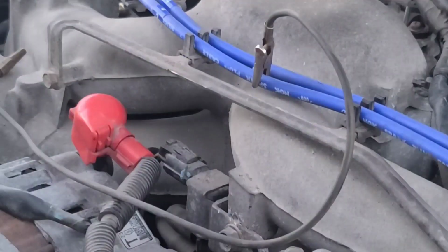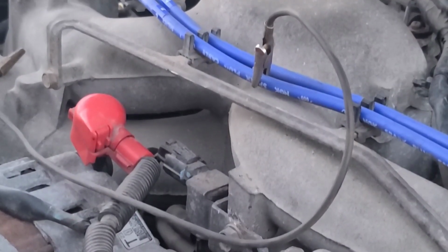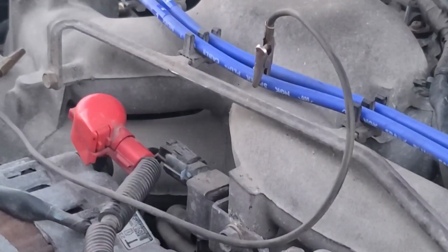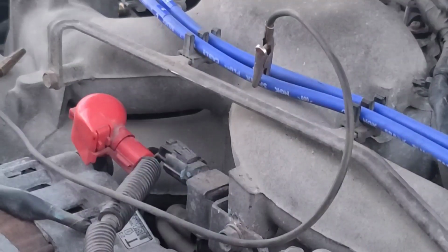So I reviewed the video and I didn't see any spark. I didn't hear anything either. Usually you'd hear a snap from the coil. I reduced the air gap to about 1/4 inch. Let's try it now. Well, that's interesting. Let me look at this video again.